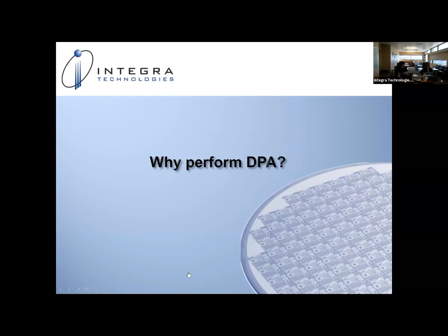So if you look at the AS6294/1 and /3, which is one for space and one for military, for PEMs, we clearly establish in that spec that when it is a new product, not necessarily new technology, a new product for a mission that you have never used before, you have not a lot of pedigree or information about the part, then construction analysis is the first thing you want to do.